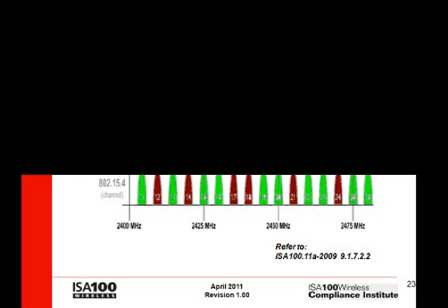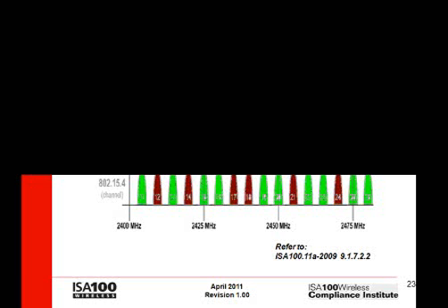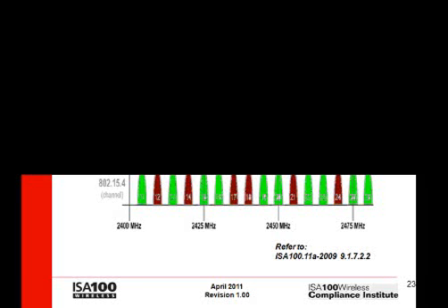For radio communication, this standard uses the IEEE 802.15.4 direct sequence radio at 2.4 gigahertz. This is the same radio used by various other standards. It was selected because it is available from multiple sources, is backed by IEEE, and can be configured to work well worldwide under a wide range of local radio regulations. The IEEE radio includes 16 channels, numbered 11 through 26, as shown in the diagram.